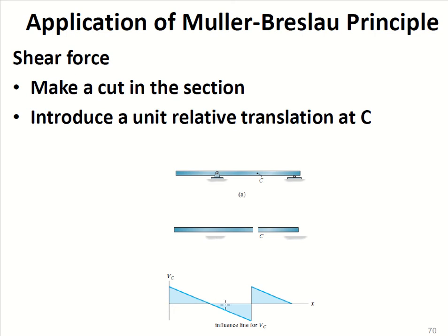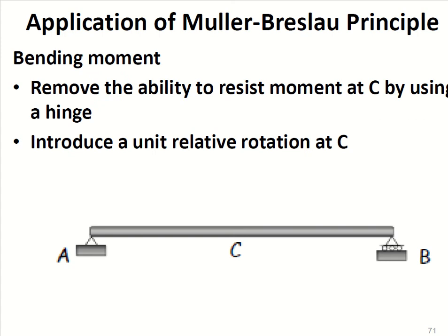See, this was the original position of the beam, and this is the new position of the beam. And similarly, if this point is moving downward, then for the shear to be in equilibrium, this point will move upward by the same magnitude. So this point has moved upward. So this is the influence line diagram with the qualitative method, right?